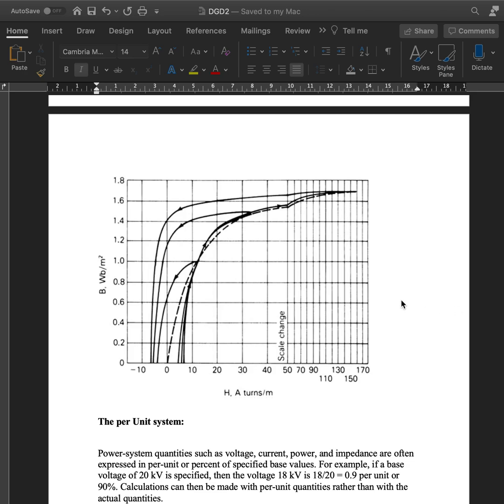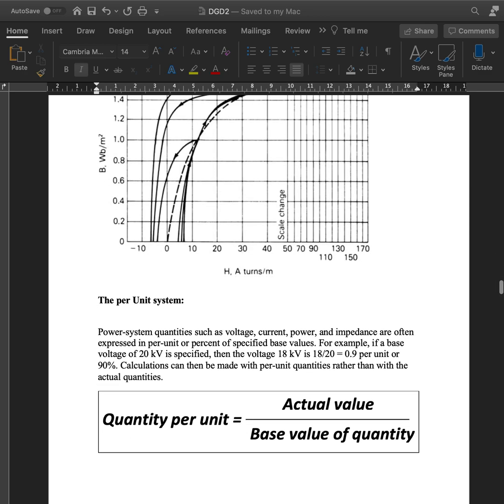There's also something called inrush currents. When a transformer is first energized, a transient current much larger than the rated transformer current can flow for several cycles. This is what you call an inrush current, and it has a large DC component. It's like a big sinusoidal thing.